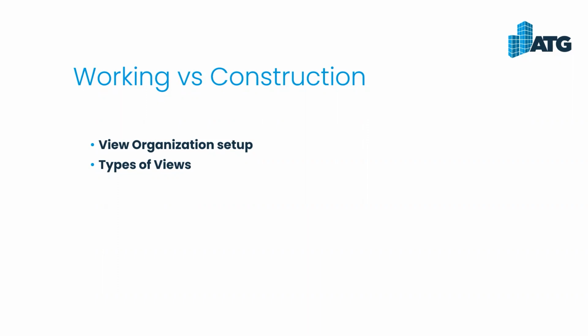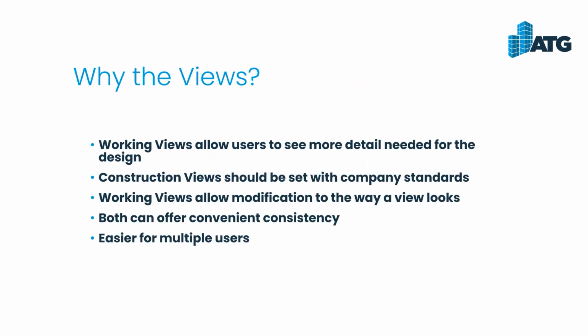When it comes to the construction documents, you may want to go in and turn off those clearances because that may be a subcategory in your object styles that you can simply turn off within those types of views. So nice thing, again, with the view templates is that you can go in and create a working type view template and also a construction type view template to display those differences between there.